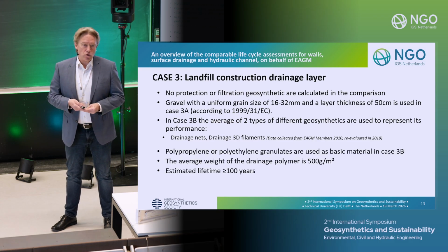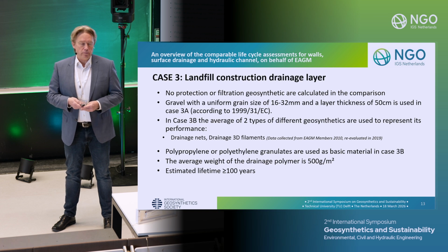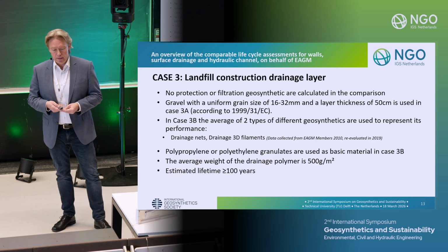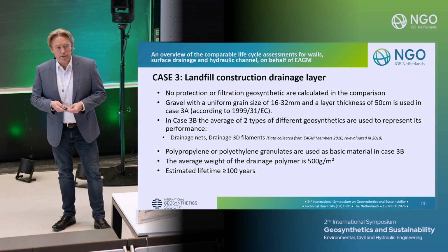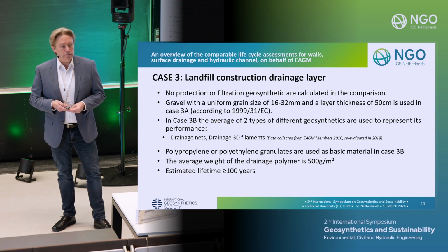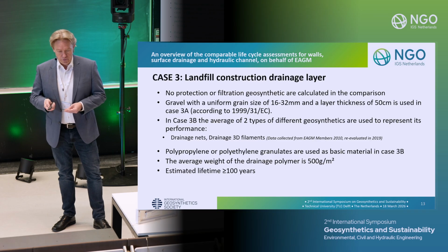The drainage core is a typical 500 gram per square meter material. Sometimes you have it a little bit lower, sometimes a little bit more. As Jürgen also explained before, we always tried to look for the worst case. The estimated lifetime for the geosynthetic solution is always 100 years. We have CE rules on how you can prove that these products have 100 years of lifetime. And this is the basis for all this.